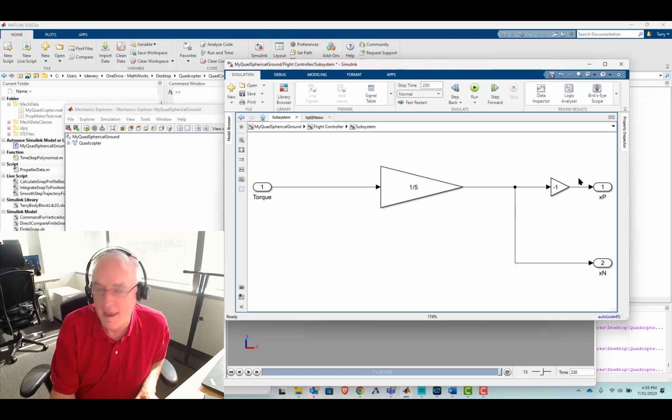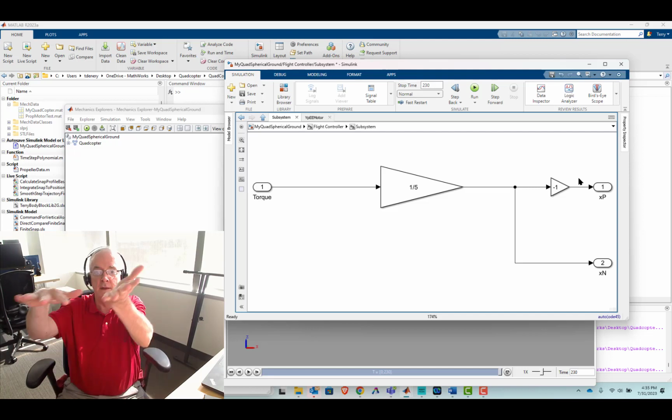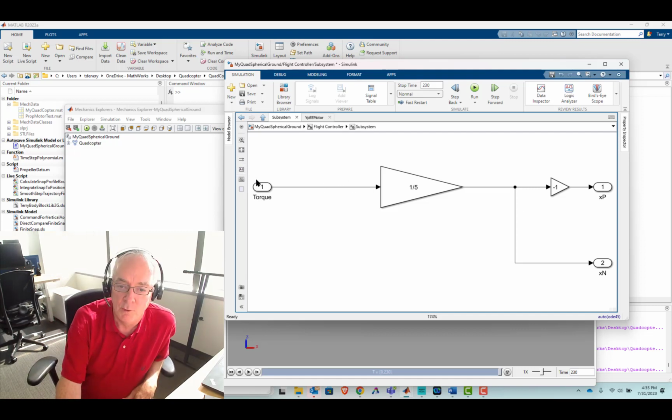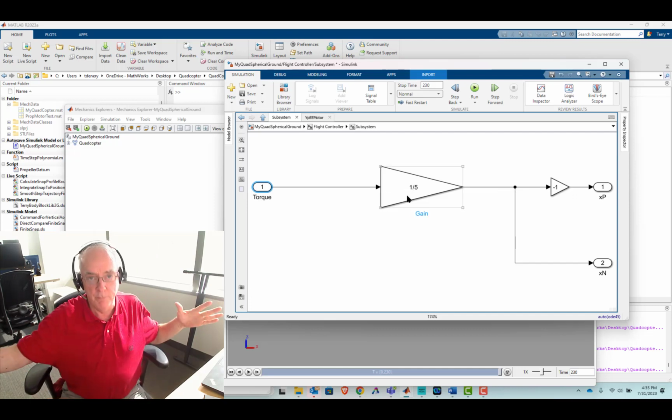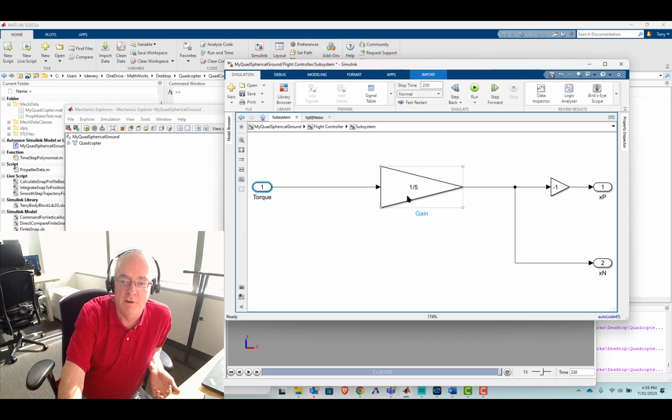They have to be equal in magnitude and opposite in sign for them not to impact the vertical thrust that we had set up earlier. The way that torque becomes thrust, at least these two thrusts, is by dividing it by the moment arm. You might recall that we set up these two bodies called beam X and beam Y. We defined them in our early videos to be 5 meters long.